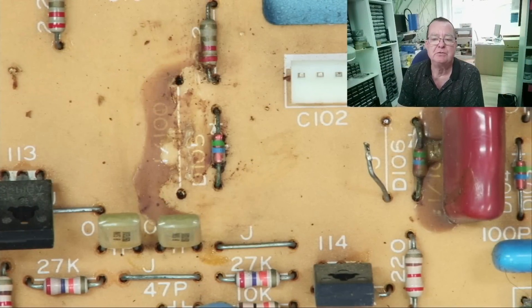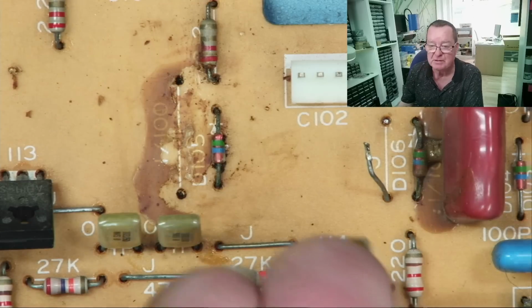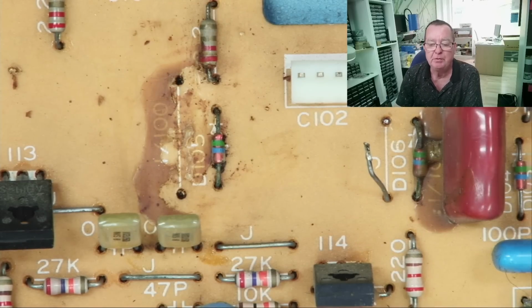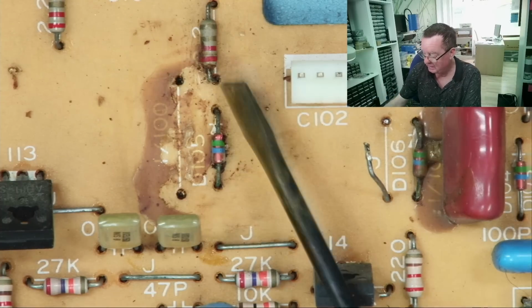I hope you guys enjoyed that. Actually, a bit of a detective story. I didn't actually expect that to be the problem, to be quite honest. But I hope you can see how we can use a schematic to find a fault like that. Even before I actually found the cause of it, we'd been through those schematics, we'd narrowed the problem down to where it was on this board, and we'd even narrowed it down using the schematic and looking for paths to ground. We'd said the only place the problem can be, in all honesty, is there.